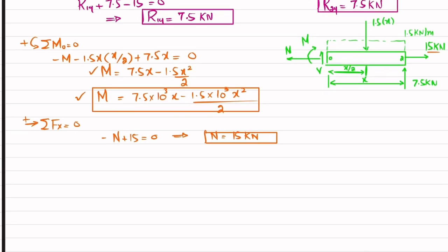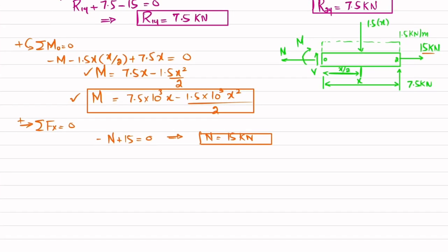So first we will find the axial strain energy. I will write it for axial load. For axial load, we have strain energy axial is equal to the integral from 0 to L of N square dx divided by 2AE, or for a single load it is N square L divided by 2AE. Clear?